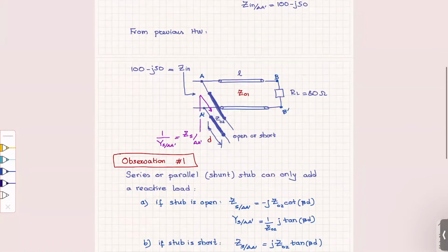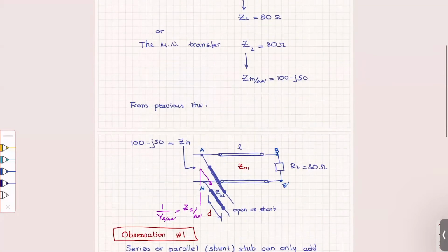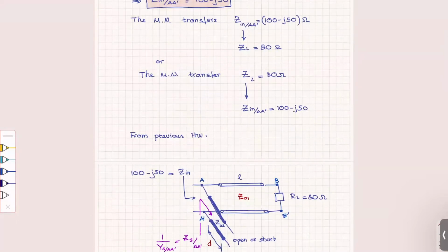So first of all, you have a real load transferred along a line. The first thing that I would do is, I will have at some point to remove its reactance, or to add reactance in this particular case. Remove reactance when I go here, add reactance when I go like that. So since I move from the load towards, I go this direction as I'm thinking about this design. So my R sub L, now it's real, will have to go through this line.